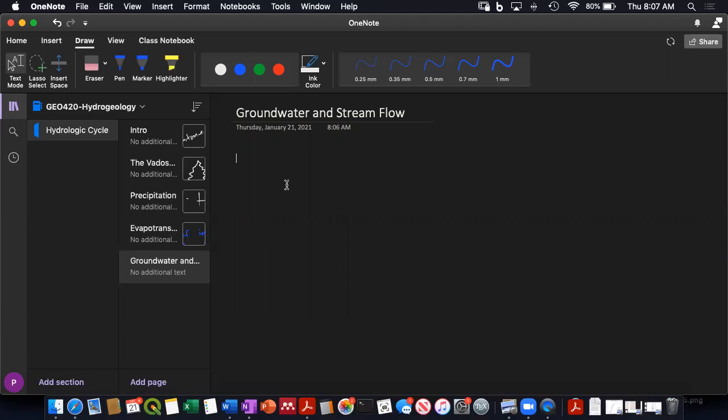All right. So the answer is, we haven't had any rain for a little while, appreciably. The snow melt in the mountains is not happening. It won't happen for another 3 months. The only source of water in the rivers in the winter is groundwater. So one way to get a feel for how active the groundwater is, when you go over these rivers, realize that right now their only source of water is the groundwater. That's it. That's an indication of how much groundwater circulation is occurring up in the mountains at all times.